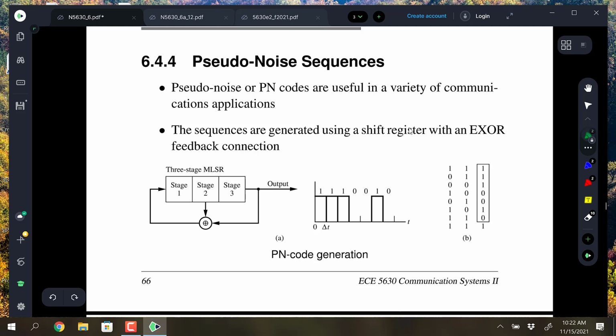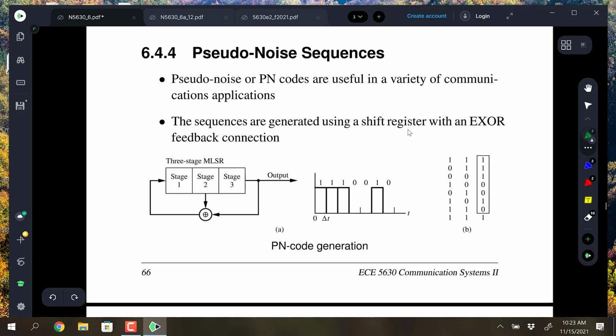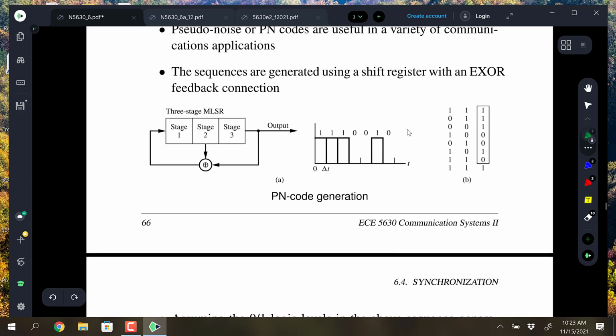And PN sequences can be used for that too. So I am pretty fond of pseudo-noise sequences, or PN, and the type that I'm most familiar with is the maximal length PN sequences, and they are talked about. Pardon me? Those are Gold codes, right? A Gold code is a special combination of two PN sequences XORed together. That creates the family of Gold codes. So they're separate. A Gold code, though, was developed from the M sequence model.